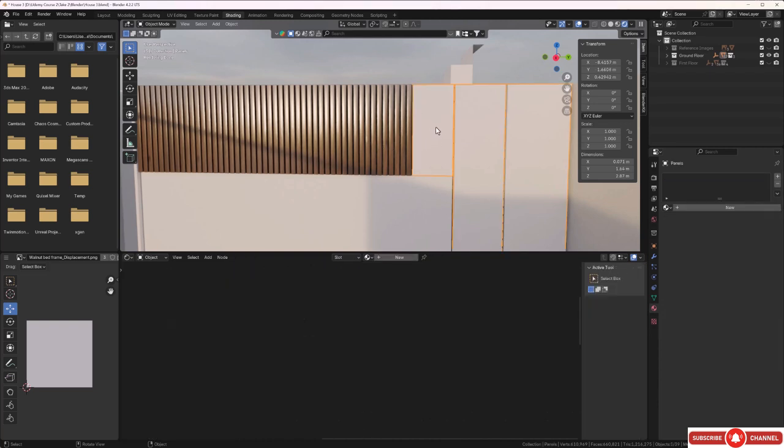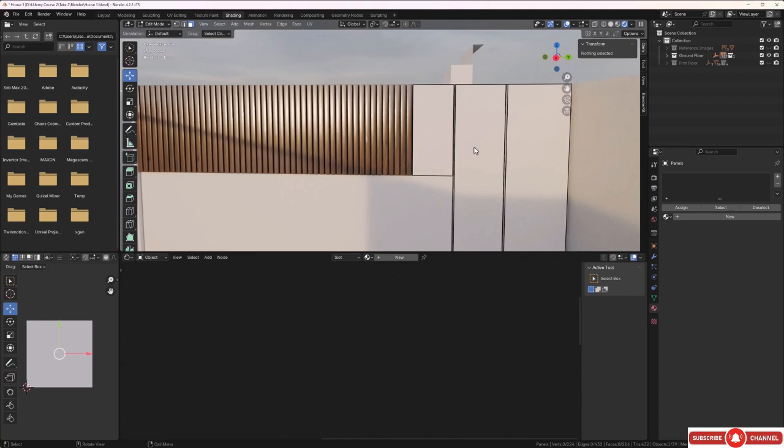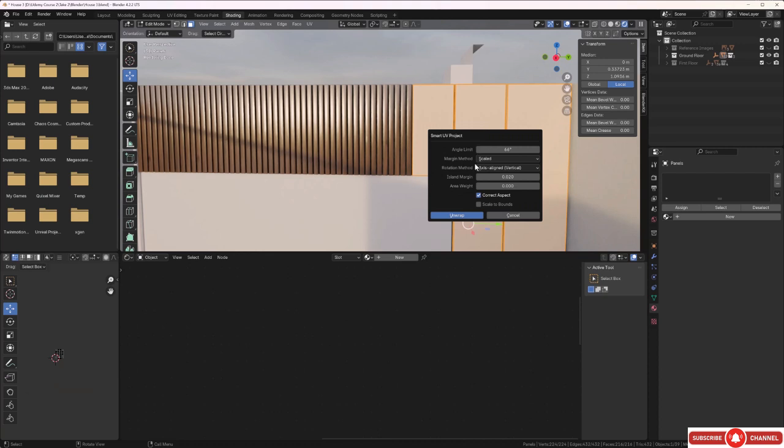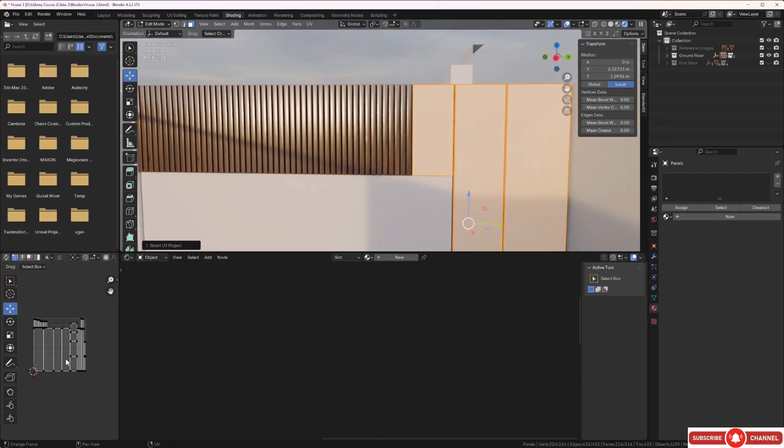So I'll grab this and let's check the rotation and the scale, and it's all good. So let's hit edit mode, hit the Tab key, and we'll press A, and we'll press U, and let's go for a Smart UV Project. Make sure you've got your island margin and go ahead and unwrap. And there we go, we should have our islands all laid out now on our UV map. So again, we already have the material, so let's hit this little drop down here and find walnut. We're looking for the walnut bed frame 01, which is the material we've just used here. And let's click on this.